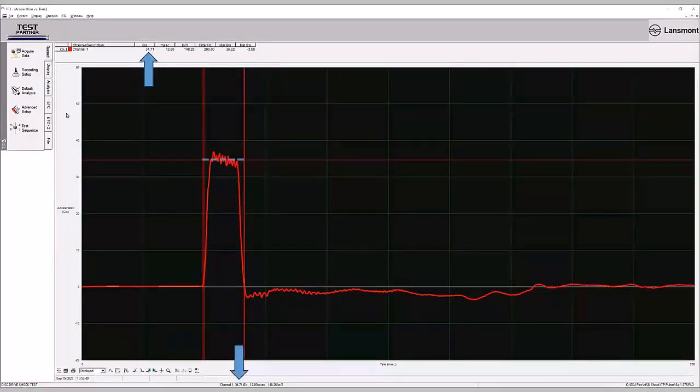And so what I take away from the data in this case is, what's the G level? What was the G level when that occurred? We're controlling the constant, the velocity change, or the area underneath that pulse. But what I'm really interested in is how many G's did it require? Remember that in the first step velocity testing, it only required like 60 some inches per second for the washer to fall off.